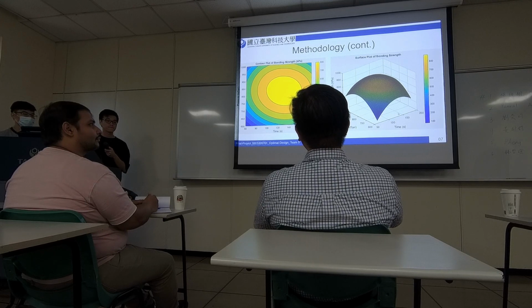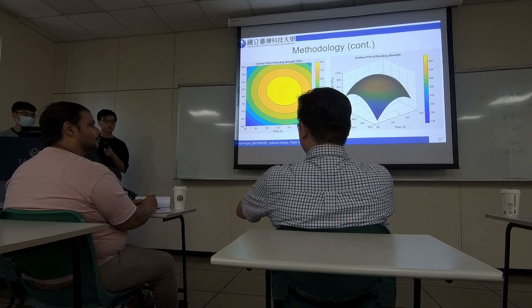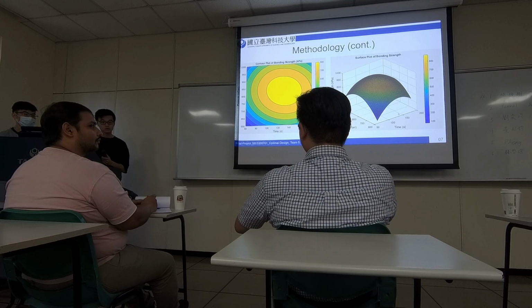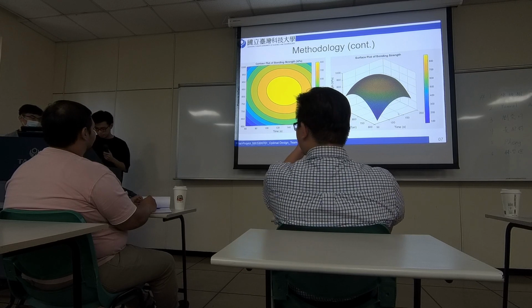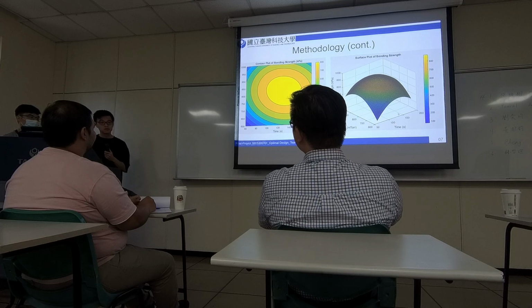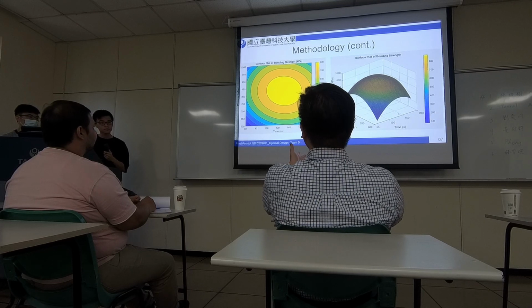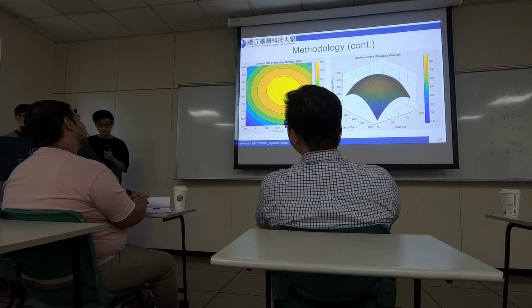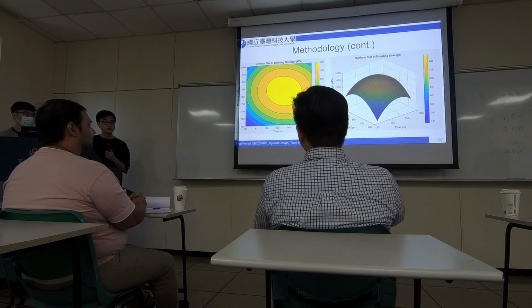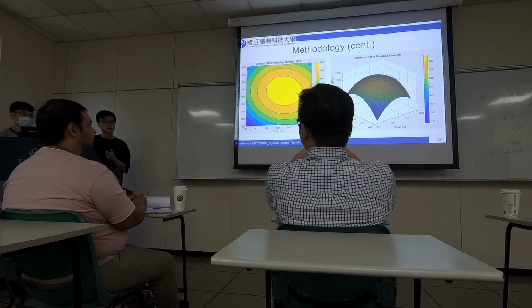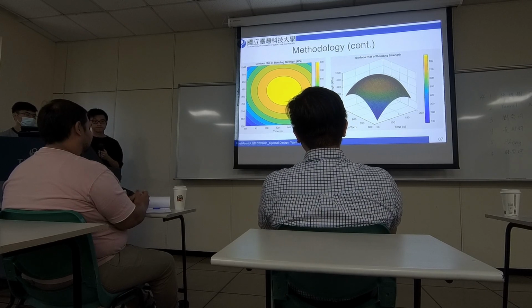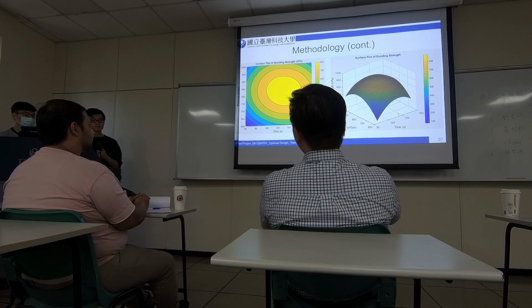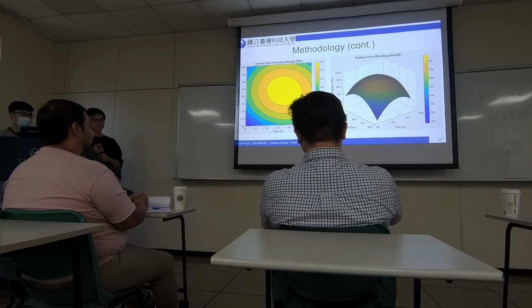In my thesis, I didn't use the burst test. I used something called a bubble test. We form a bubble by pumping air into the device. But I think for your case, the burst test is better because your purpose is to make a microfluidic system, so the boundary condition is similar to your final device. Okay. Maybe later on when you have issues, we can have more discussion. Okay. Any comments?